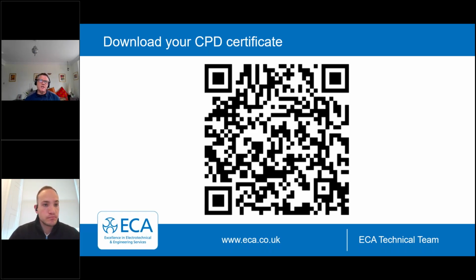Oh, that is a really good question. Well, either or, I guess. Design data would give you the information, but there is testing and how to test detail in 5266. Previously we used to do it the old-fashioned way, plot out grids and use verified and calibrated lux level meters. It's sort of an either or, really, as long as the manufacturer stands by their design data and gives you a statement along those lines, or you could verify it in the field by manual testing.